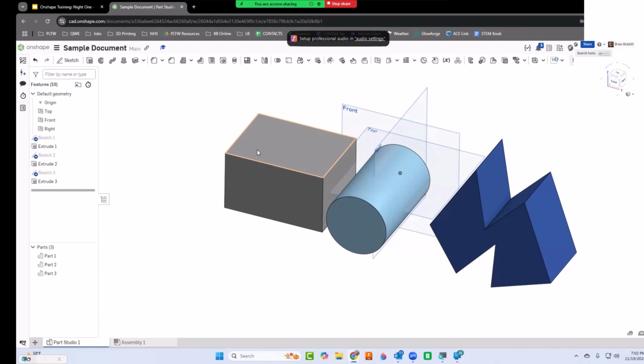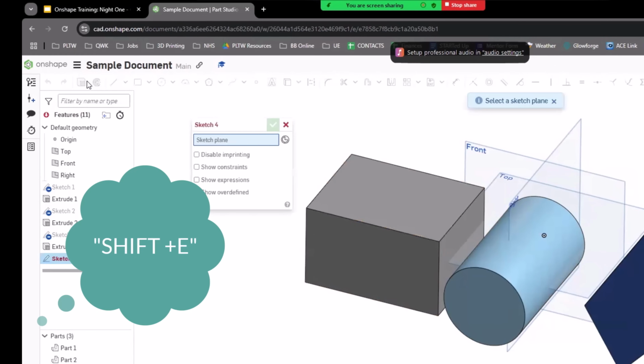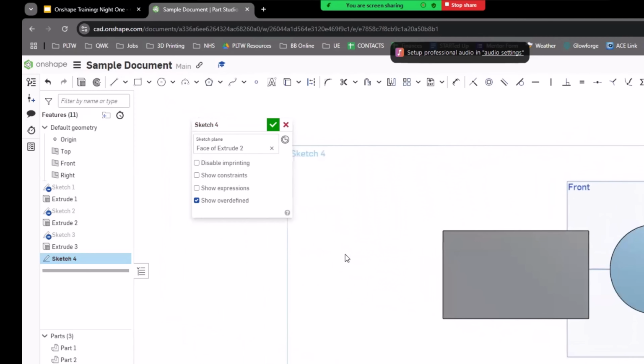Let's take this rectangle here and let's put some holes in it. Let's go Swiss cheese up on it. So I'm going to say sketch. I'm just going to click any side of the rectangle. So I'll start here. And I'll press N to normal it. And then I'm just going to take my circle tool and I'm going to draw some random circles.